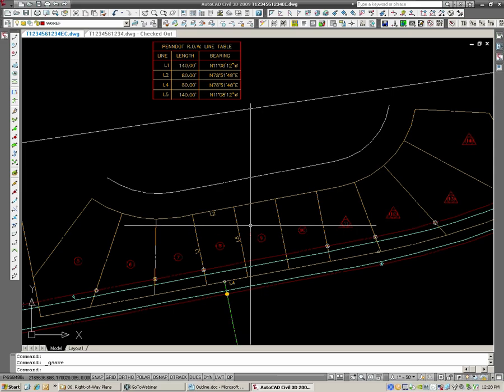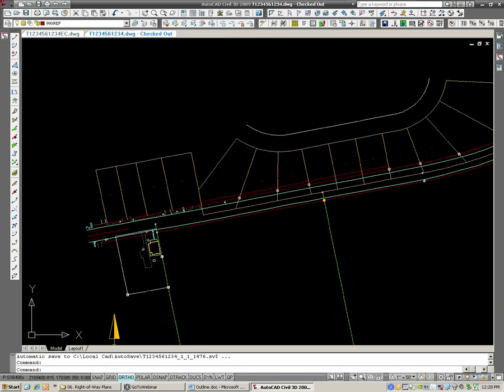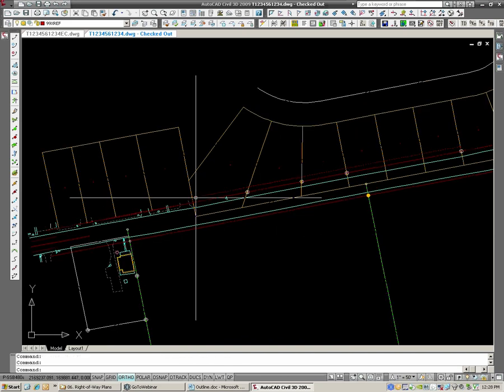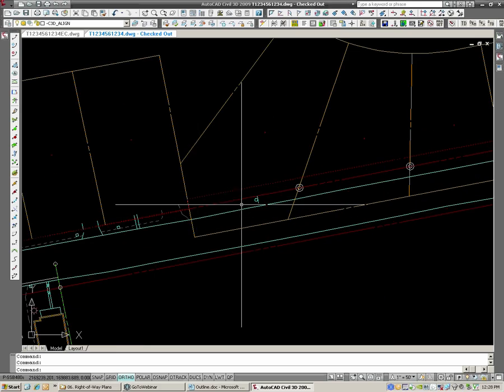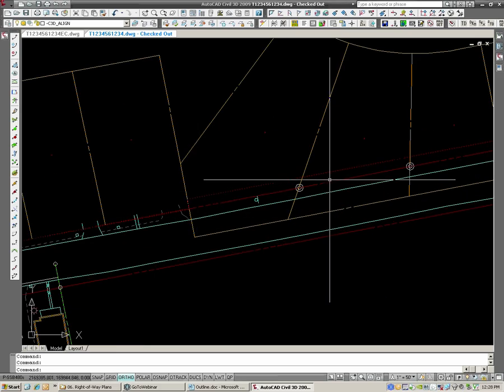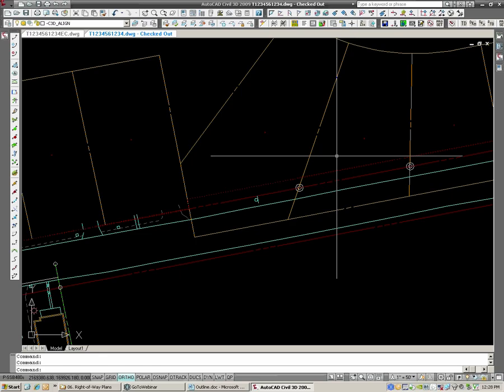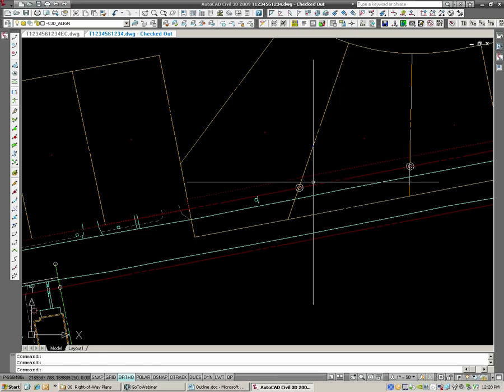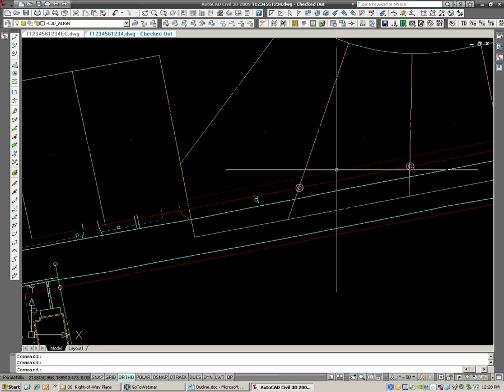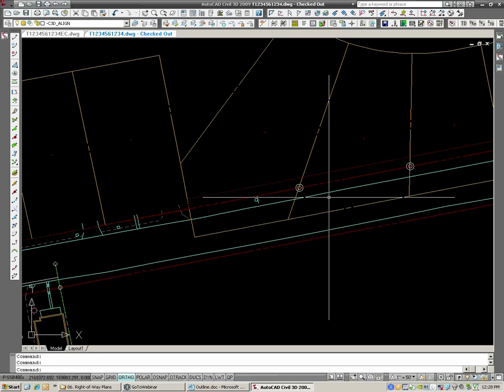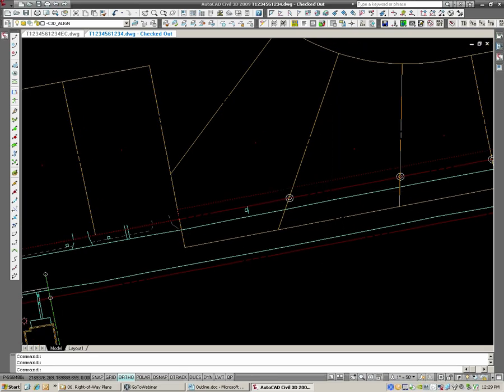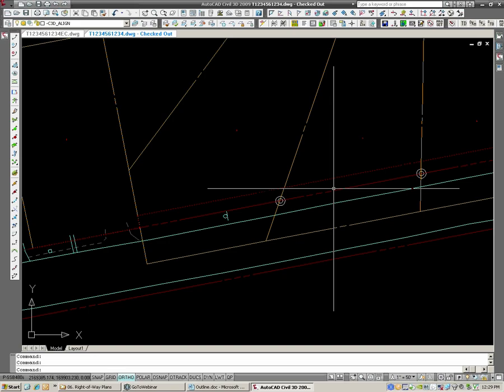Let's talk about the proposed and the actual take. I'm going to switch back to my T file here, my transportation design file. And in this file, what I need to do is actually incorporate this right-of-way line in and see what that splits these parcels into. You know, how much area in each portion of the parcel, since I'm going to take this entire area through here. So I'm going to sort of clean up the old property and also take an additional 10 feet from the right-of-way.